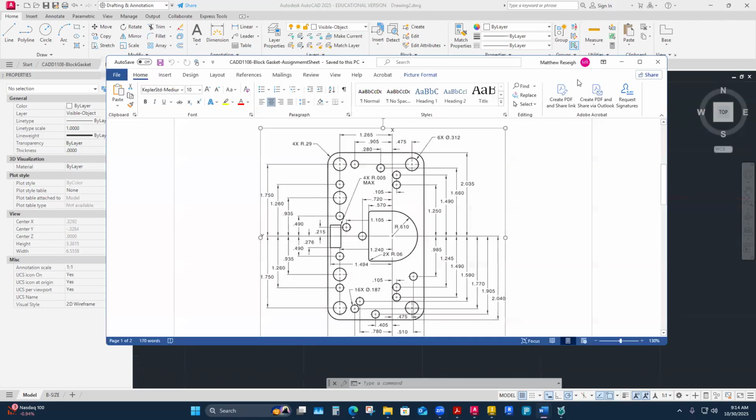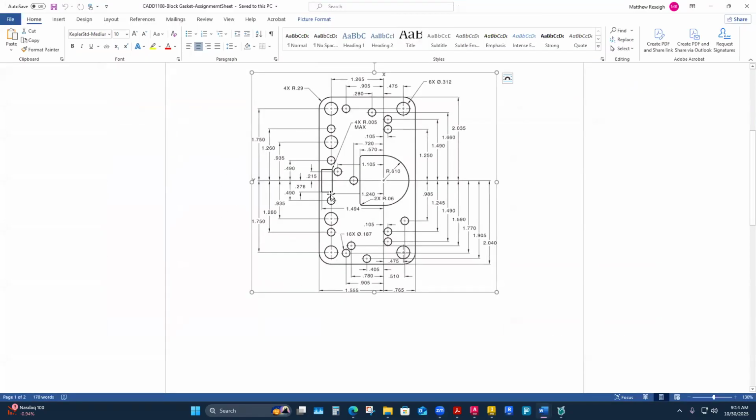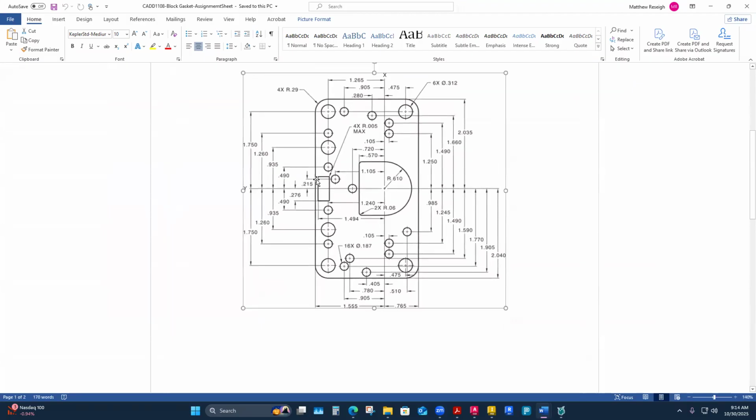Yeah, and so just like not trusting the thing. I'm looking at my rectangle here now, and I'm gonna start drawing this, but it really is only located to one side, right? So I'm gonna assume this is dangerous, but there isn't a dimension different in the X direction here from center this way or this way. So I think I put mine as both 2.76 off of the Y axis here. So that's where things are not totally the same. It's a little bit dangerous to think that that's centered over center line.